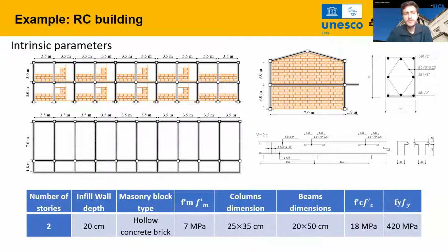And the intrinsic parameters in this sense refer to the distance between spans, all the geometrical characteristics, the internal reinforcement considerations and characteristics of each one of the elements, and also the mechanical properties of the masonry infill walls and the mechanical properties of the reinforced concrete elements.